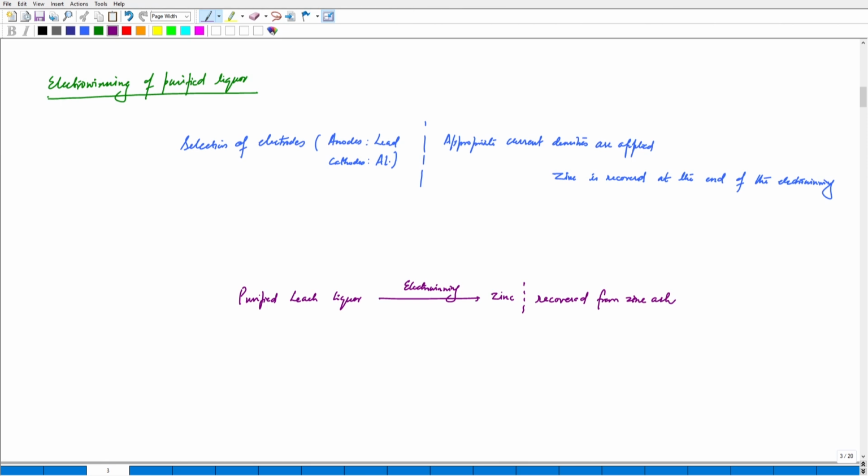So, till now we have seen and we are able to understand that it is very important to holistically think about processes from multiple facets. What is the first step for zinc ash recycling? Basically, for the hydrometallurgical route it is leaching, followed by purification, followed by the electrowinning process.